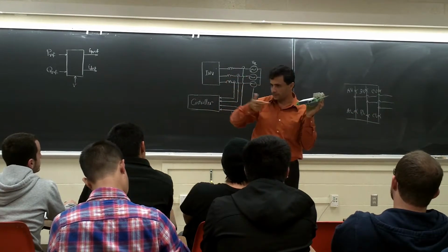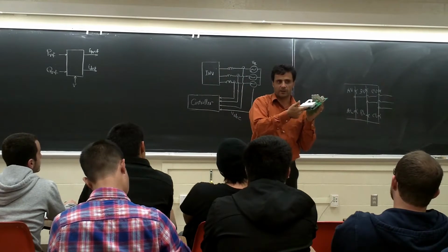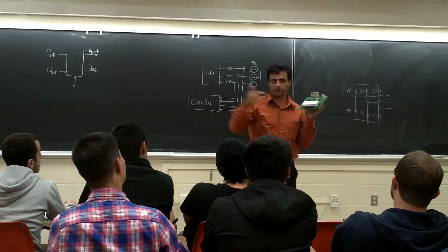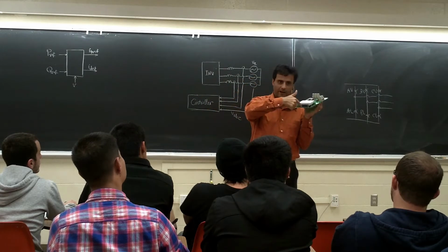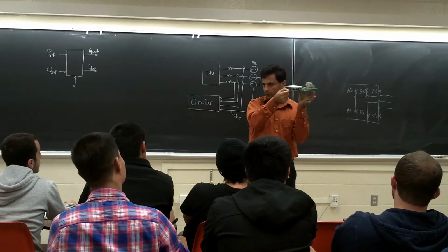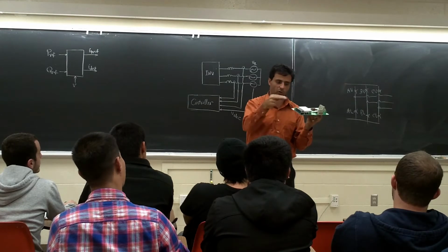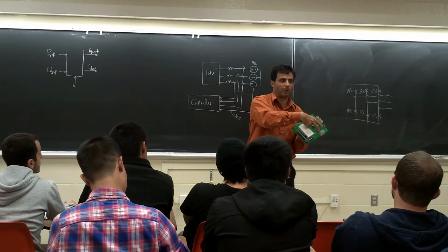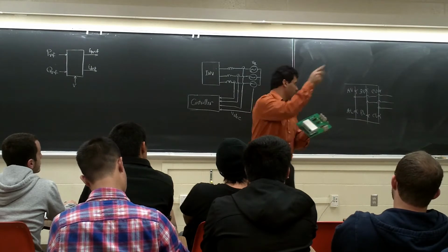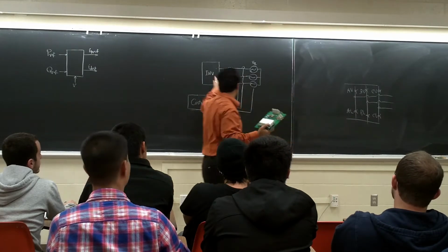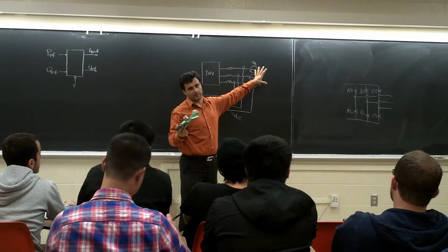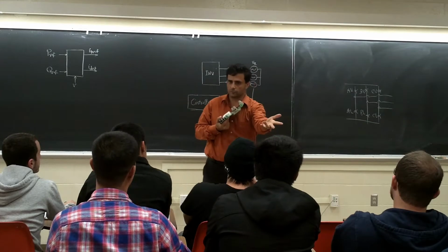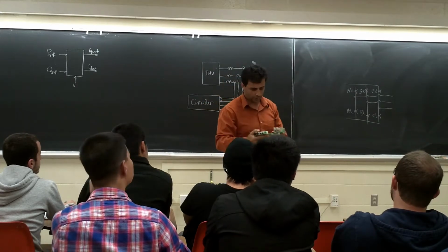We talked about it, right? You bring it to here. This is a kind of expensive way, but very, very safe. You bring the signals from your control board to the inverter, right? This is all power. This board is all power. The control signals come here, go to the gate driver, and connect to the power module, right? And the power module, this side goes to the output filter and the grid, right? That's one side. This side goes to the DC source, whatever it is, battery or solar.